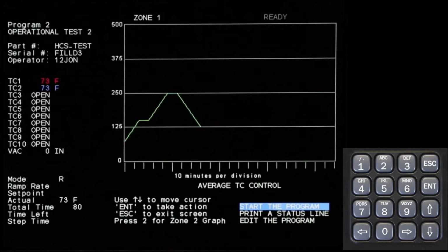8-step cure configurations are available on bonders configured for multi-step programs and will have a different interface for editing programs. Each step is selected from the list by highlighting it with the cursor and pressing Enter. A pop-up menu will allow entry of the ramp rate, dwell temperature, dwell time, temperature deviation, and alarms for that step. The graph screen presents a graphic representation of the cure.